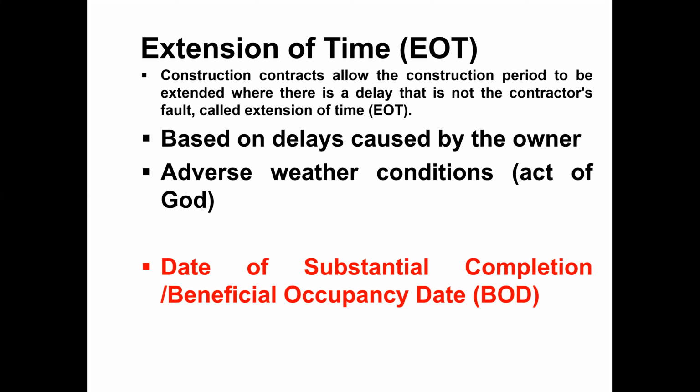When the time is mentioned in the contract, it runs from the notice to proceed. The starting time will be mentioned, and the completion time will be until the substantial completion. After the substantial completion, that time will not be counted in the contract time.